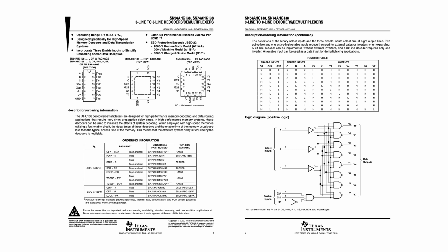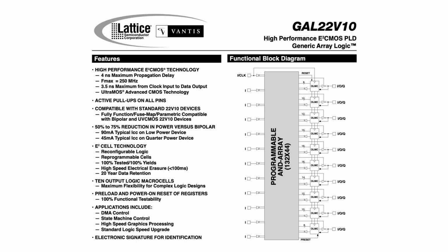Now, I started putting together a decoder design using standard 7400 series logic ICs. The 74AHC138 decoder is fast enough, but complete decoding required several additional logic gates, especially for the fixed RAM, plus an additional stage of the 74AHC138s and some address line inverters were required to decode the IO space region. The result, of course, was that both the decoding time and the chip count were ballooning. So because I've already used a GAL 22V10 in the Playgrounds design, I figured it couldn't really hurt to see what it would be like to use it for the address decoder.